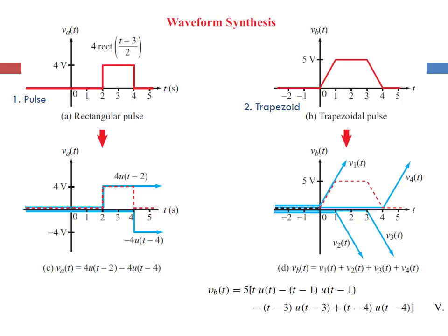And now we need another ramp function to have it go down, and then we need another ramp function to cancel the downward function. So if you look at the wishbone kind of thing underneath there, you can work through it. 0, 0, 0, and then we have our increasing all the way to 5 volts, and then we have it holding steady at 5 volts, and that's been done by the second signal that points down